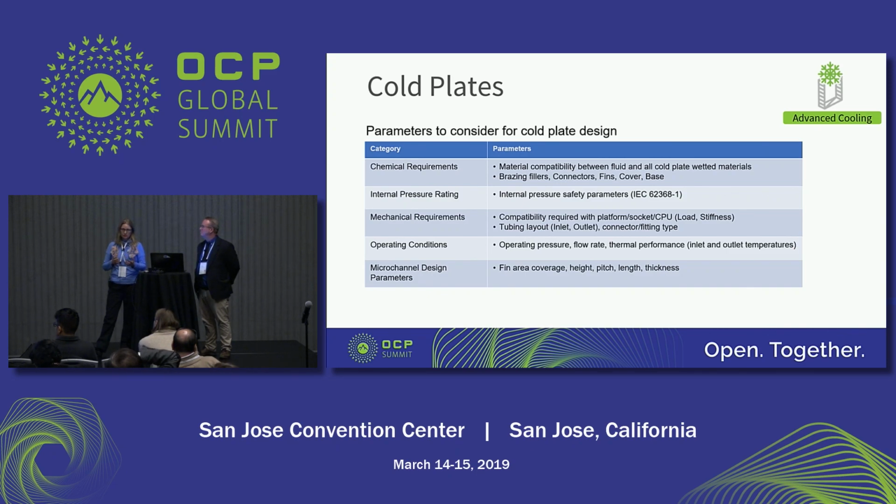You need to understand your operating conditions, the operating pressure, flow rate, what temperatures you can really allow, both inlet and outlet temperatures. And for the microchannel cold plate design, the parameters to vary there are really fin area coverage, the height of the fins, the pitch, the length, the thickness of them, in order to generate the design that you need.